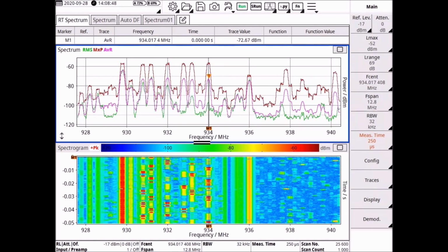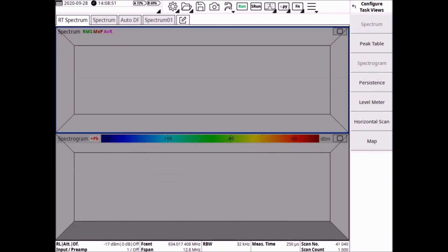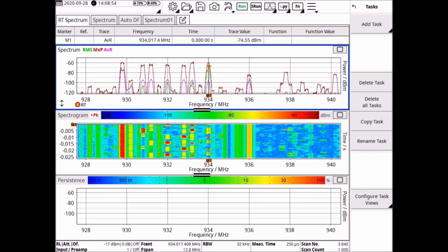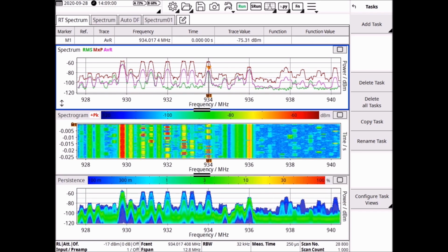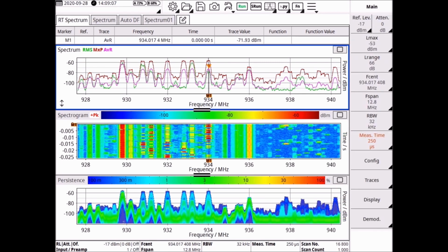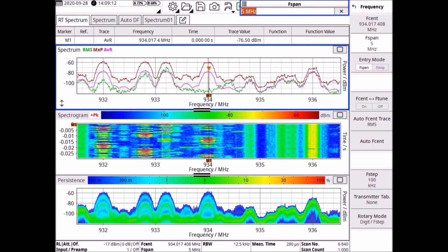Such analysis, with various views onto the signal and possibly corresponding demodulation, is an important helper to conclude on the eventual interference source, and it also increases our experience to better deal with future interference issues. Typically, interference by faulty electronics behaves fluctuating and doesn't show any clearly limited bandwidth.